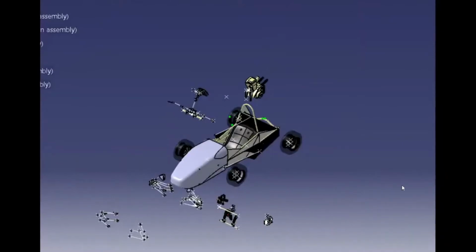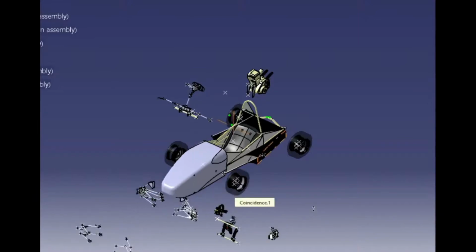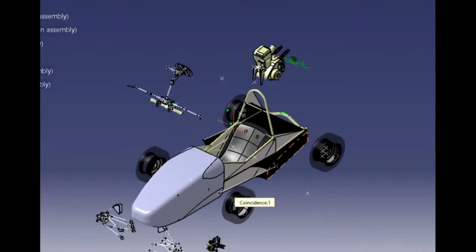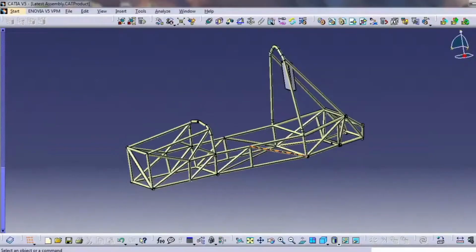Now, as we saw the transmission system, let us move on to another very important system, where every subsystem is going to be fitted, that is the roll cage system. Now, in our vehicle, the main aim and objective of a roll cage is to make it compact and as light as possible and reduce the members as much as possible while satisfying all the rules. We have to satisfy every single rule related to the roll cage, and plus keep it as simple as possible.